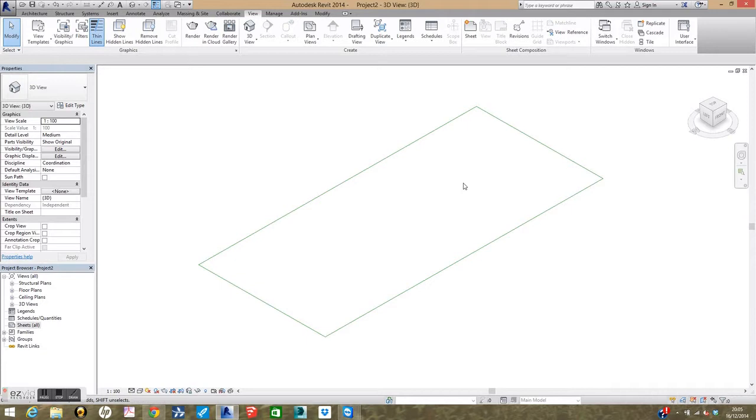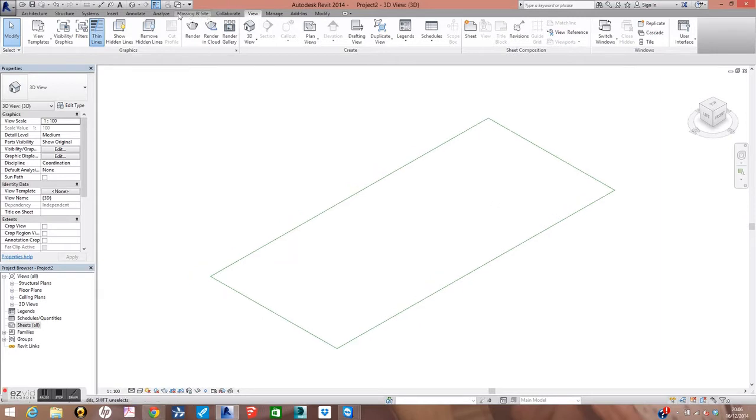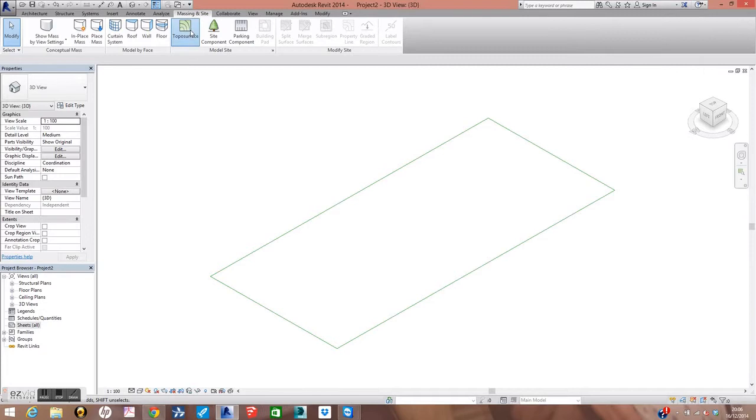So, for the purposes of this tutorial, as I said, I'm going to quickly show you how to make a very simple set of road geometries which correspond to a topographical surface. So we'll still be using the topographical surface to control the elevations of our roads, but we will be using massing tools and roof/wall appendages set to massing surfaces to create our roads. So let me just get into this, and hopefully this will help you all out.